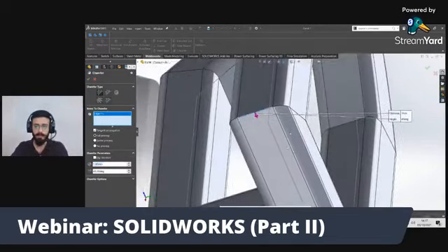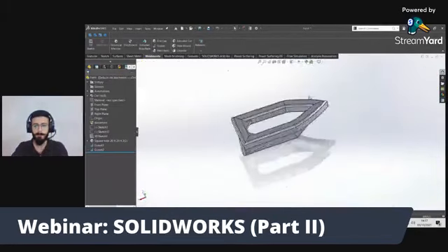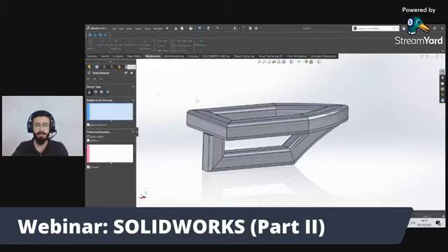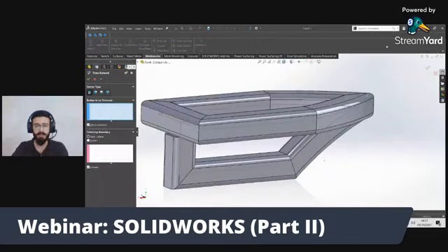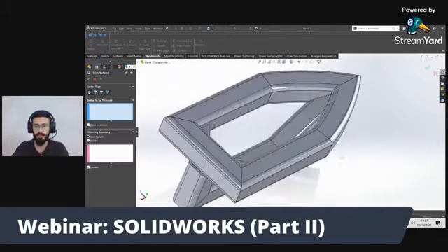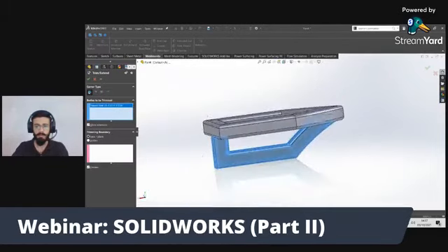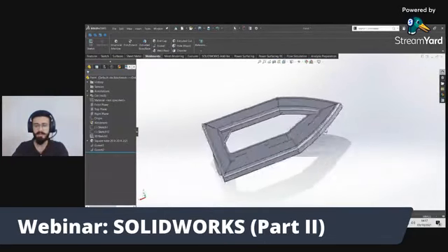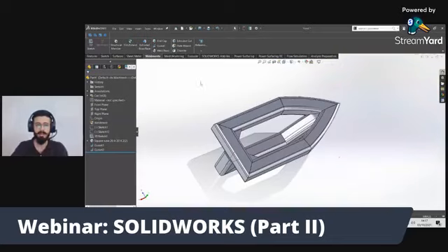Now it's not possible to make a weldment here, so just leave it. This is our weldments. Extrude cut is the same, extrude boss is also the same. Trim extended, like if there is an extended object from here, it can trim it for you. There is no extended from here. Like if I select this, it will trim the whole body. There are no extended faces here, so there is no use of the trim feature here. So this is for our weldments.